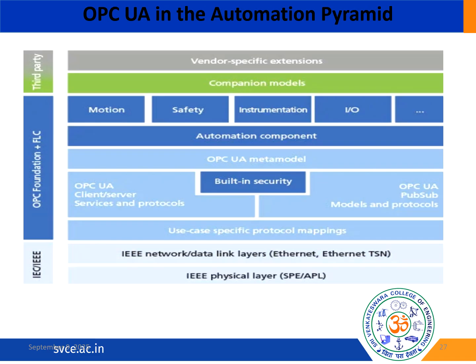So we have PLCopen. It represents the association of IEC 61131-3 based controller manufacturers. It has collaborated with the OPC Foundation to define corresponding OPC UA client function blocks. So it has created a way for PLCs to exchange complex data structures horizontally, and it can also include other controllers, or vertically through OPC UA servers in a manufacturing execution system.